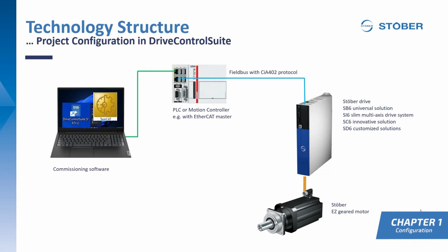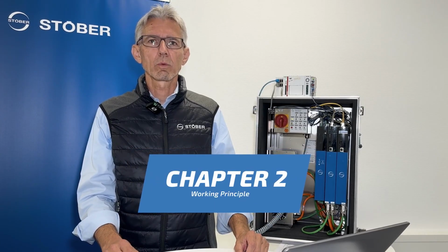The great thing about CiA 402 is that it is a globally standardized device profile for controlling drives, which has proven itself over decades since the days of CANopen. And it is also described in the international standard IEC 61800-7 for EtherCAT. Now I'll show you how CiA 402 works.